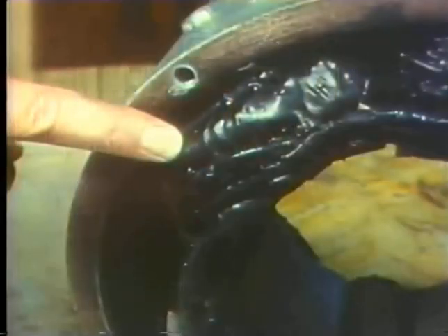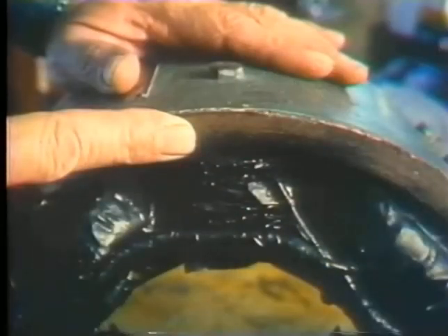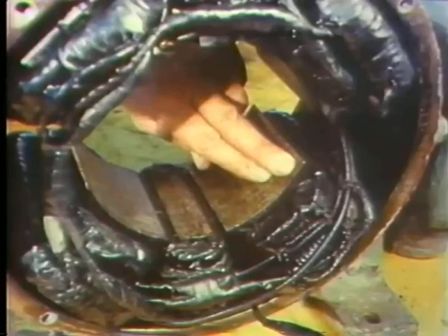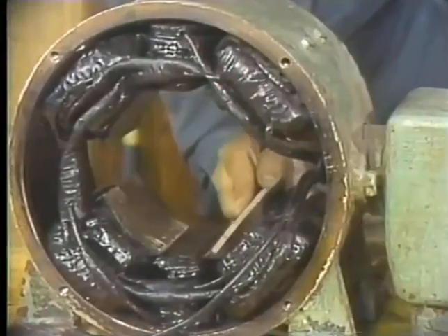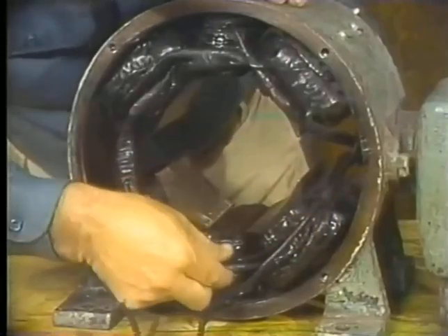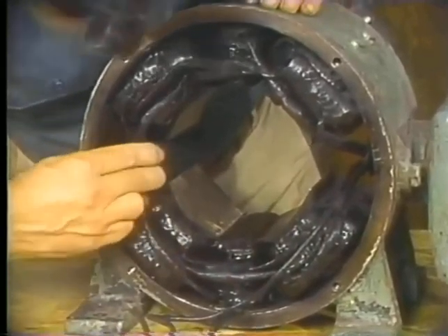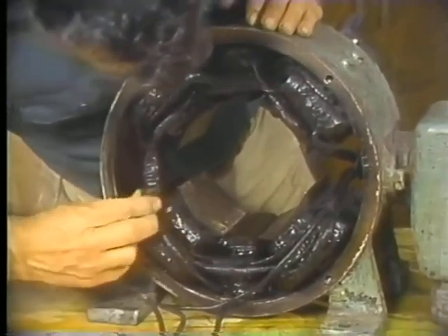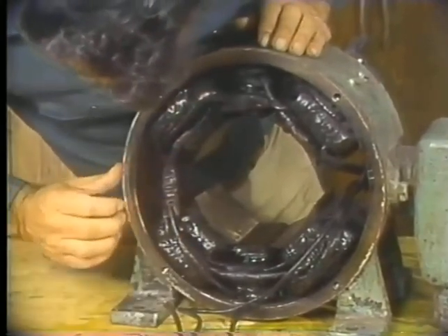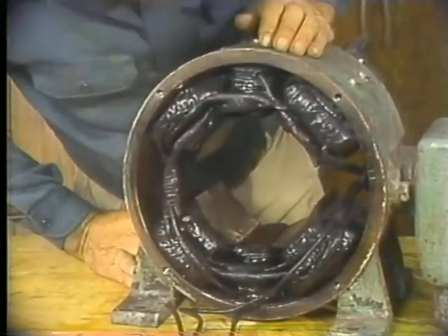Okay, now it's time to check the field coils. Carefully inspect them. Look out for cracked or broken insulation. Be sure to examine the interpoles too. Repair any damage to the insulation using the insulation varnish. Check the pole pieces for dents or burrs. Use a file to remove them. Then, check all field coil connections and coil leads for damage. Check the insulation here as well for cracks or breaks and repair as needed. Check each connection for tightness.